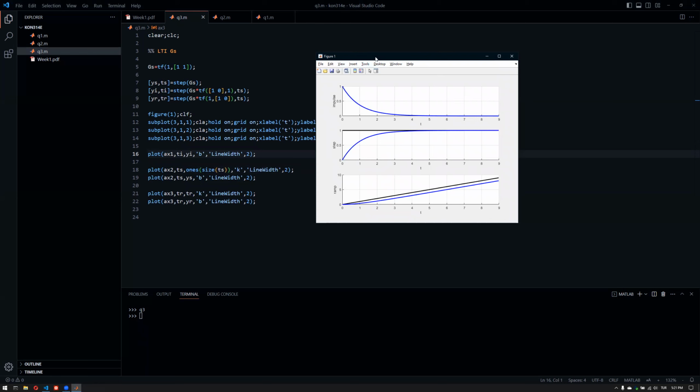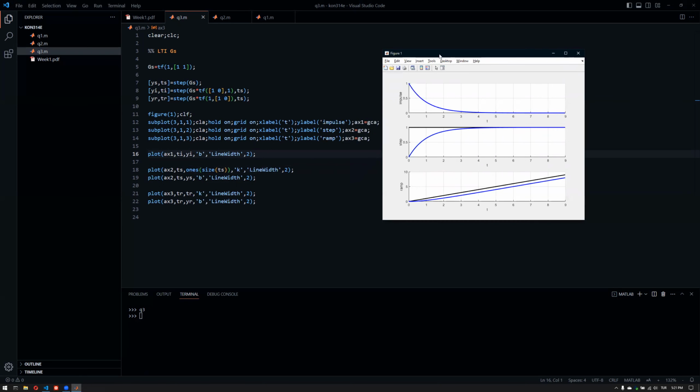And I didn't need to open up Simulink and drop down the derivative or the right source for impulse and ramp and so on. I just utilized the fact that if I take the derivative of the input, the system's output will be the derivative of the output. Or if I take the integral of the input and apply it to the system, if the system is LTI, the output would also be integrated.